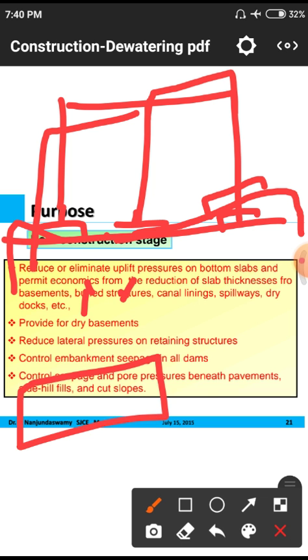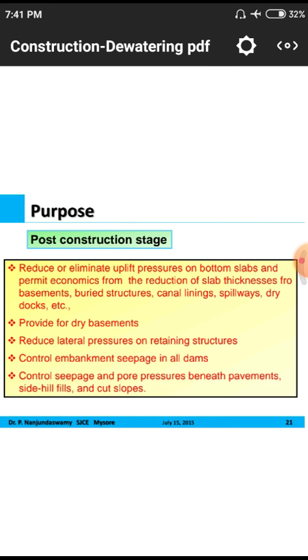will bear some amount of cracks due to these settlements. Uplift means we observe these cracks in the bottom surface. So if the structure is to be retained as a crack free structure, we have to focus on these uplift pressures. If the uplift pressure is more, automatically the structure has to face more cracks.